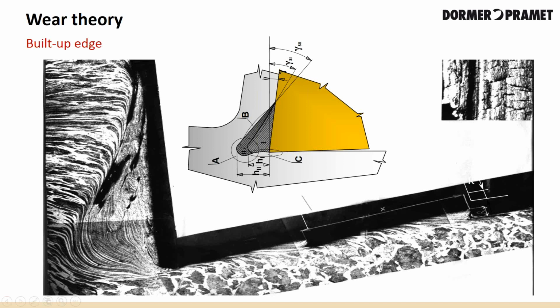And you can see this as an actual picture here. The black portion and the white is the edge of the insert, and the melted portion to the left is the material itself that has already attached itself to the face or the edge of the insert itself, and you can see that in the picture up here as well.